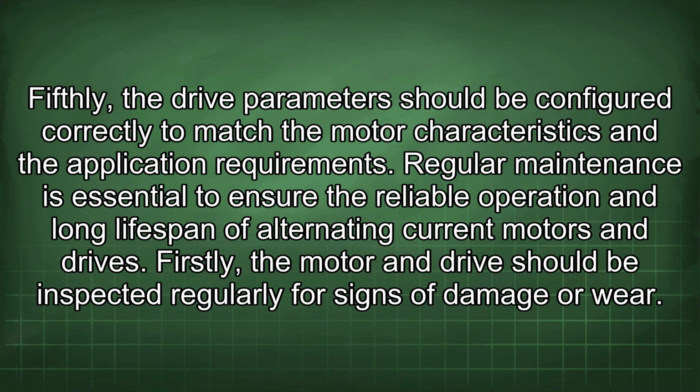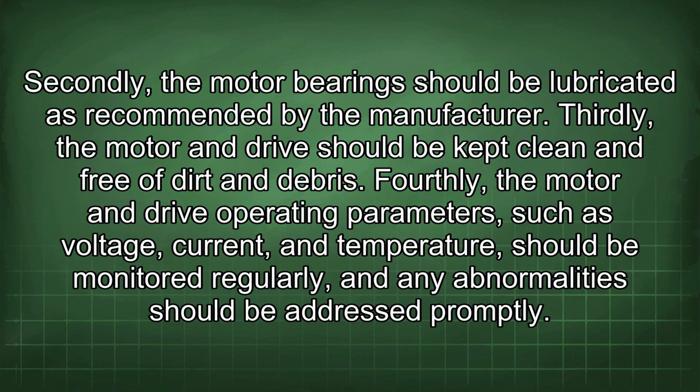Regular maintenance is essential to ensure the reliable operation and long lifespan of alternating current motors and drives. Firstly, the motor and drive should be inspected regularly for signs of damage or wear. Secondly, the motor bearings should be lubricated as recommended by the manufacturer. Thirdly, the motor and drive should be kept clean and free of dirt and debris.